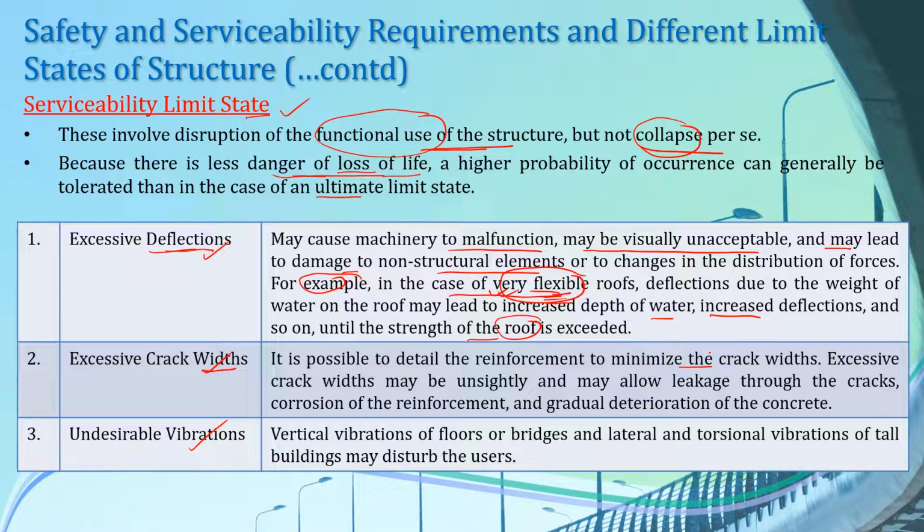But when those crack widths exceed the specified limits, then that may be unsightly for whoever sees those cracks, and those cracks may even allow leakage of water. And that leakage of water may even cause corrosion to the reinforcement, and as a result, there may be gradual deterioration of the concrete.